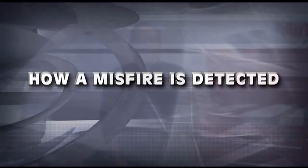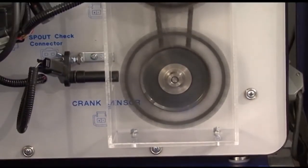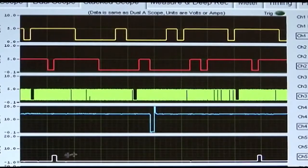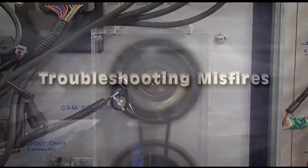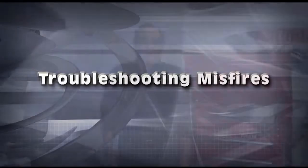Most misfire detection is based on the assumption that crankshaft rotational velocity varies as each cylinder contributes its power output. When an engine misfires, the crankshaft slows down a little bit. When the OBD2 system detects a high enough rate of this slowdown over 200 engine revolutions, a misfire code may be set. If you have a misfire, the check engine light could be on.